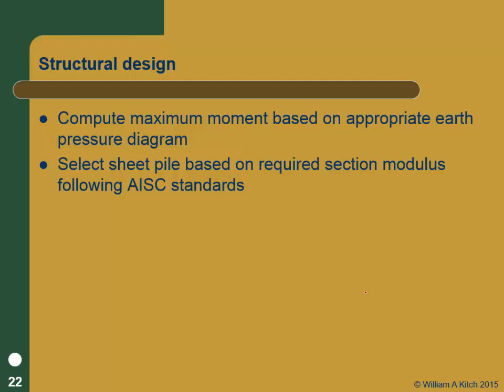Let's talk about assumptions quickly. What are some of the assumptions? There's a real important implicit assumption in these design methods that we haven't talked about. We talked a lot about it in gravity walls, but we didn't bat an eye about it here, and it has to do with the active and passive pressure. What's the implicit assumption? Well, we are generally using Rankine and ignoring wall friction. That's correct. If you want to, you can use a Coulomb analysis and put in wall friction.